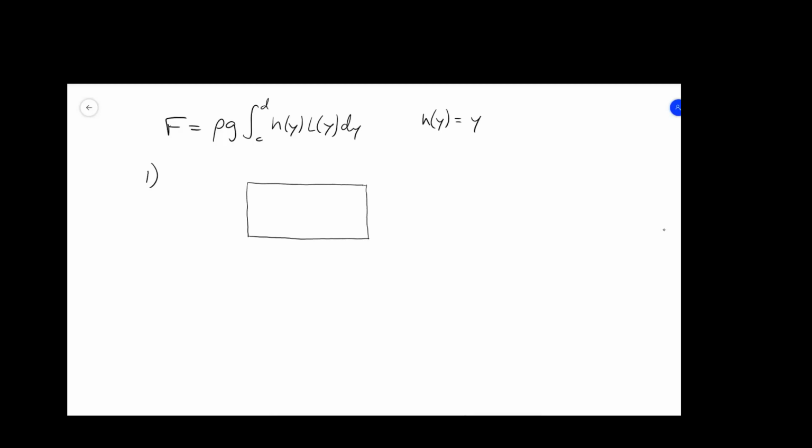So we're assuming that this tank is full of, let's just say water. It doesn't say what's actually in it, but let's just say water. And it says feet. So for water, rho is equal to 62.4 pounds per cubic foot. That's the density of water in the English system. In the metric system, it's 1,000 kilograms per cubic meter. Usually, I should have put that in the problem, but I didn't put it here. Anyway, I'm giving it to you now so we know.